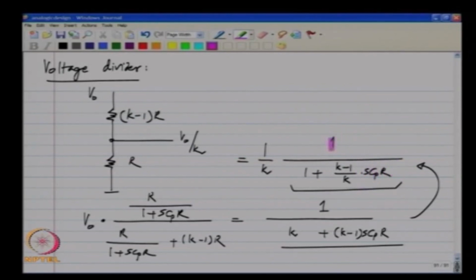At very high frequencies, because of this capacitor Cp which acts like a short circuit, even if the voltage has a high frequency component, that component will be shorted out to ground and you will see nothing at the output.